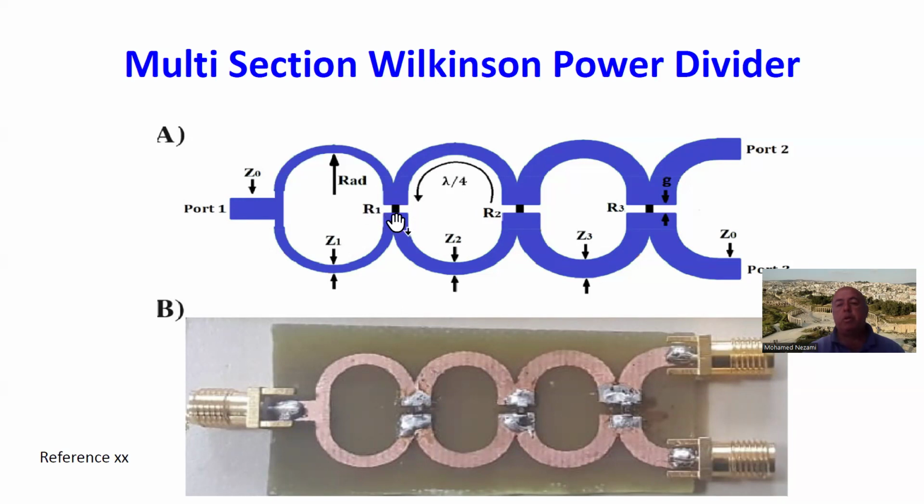Now, this is a surface mount resistor, if you're not doing a thin film implementation, be it strip line or microstrip line. The length of this resistor and its parasitics turn out to be a big deal, because that's really what limits the performance of these splitters for the broadband case.